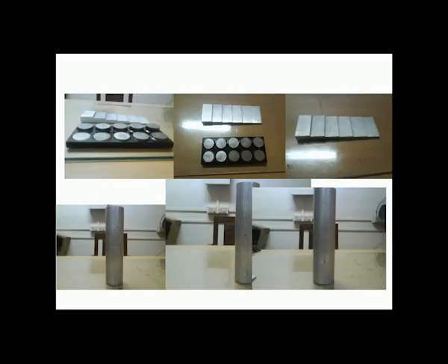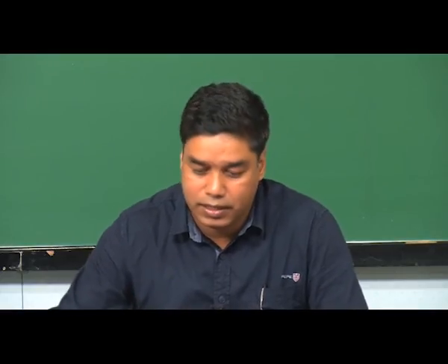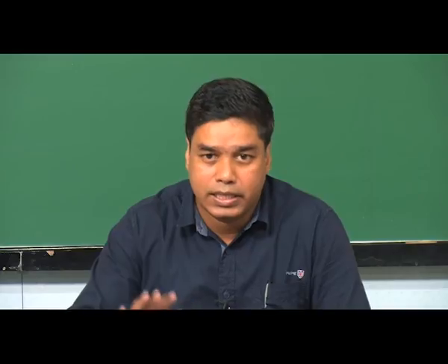Okay. So, like this you can make this kind of artificial flaws on these reference standards or these standard blocks, and since the location and the depth of these defects are known, you can get an echo from each of these defects and then see on the display screen whether that echo is coming at the place or at the time where it is supposed to come. Okay. So, like that by collecting the data at different depths you would be able to calibrate the instrument.